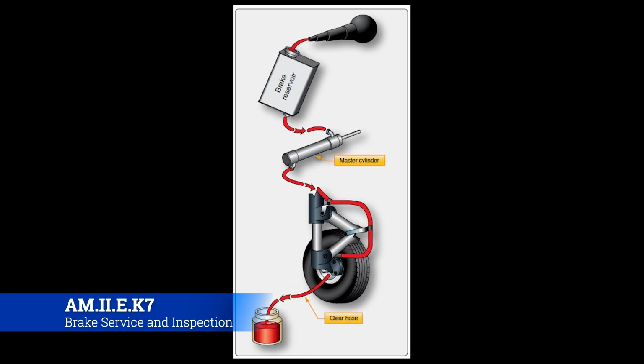Once you get a steady stream of brake fluid out there, you turn it real quick, and that basically seals up that line. All the air has come out, and all that's left inside of the line is just charged brake fluid or hydraulic fluid, in our case 5606. And then you'll service the reservoir, make sure that all of the brake fluid is topped off where it's supposed to be, and then you have a fully healthy system.